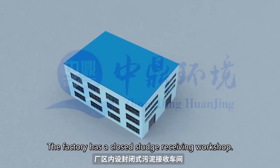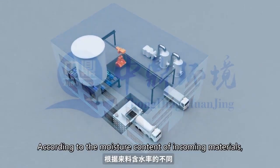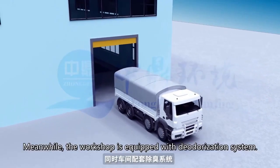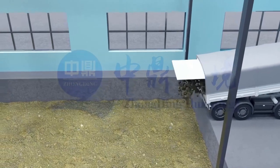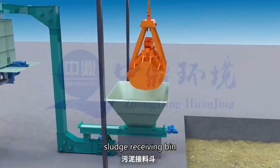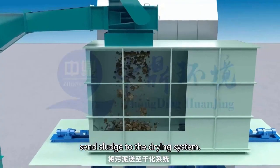An enclosed sludge receiving workshop is set up inside the factory area. Depending on the moisture content of the incoming materials, sludge collection systems for both 80% and 60% moisture content are installed, and the workshop is equipped with a deodorizing system. When unloading, 60% moisture content sludge is stored temporarily in the material pit. Equipment like the grab bucket, sludge receiving hopper, scraper conveyor, etc. is used